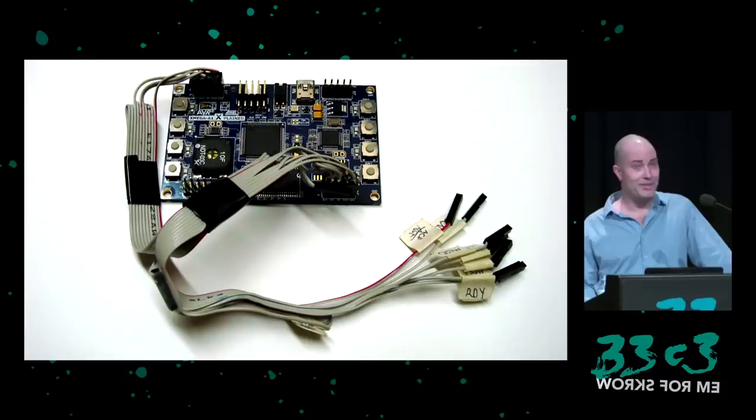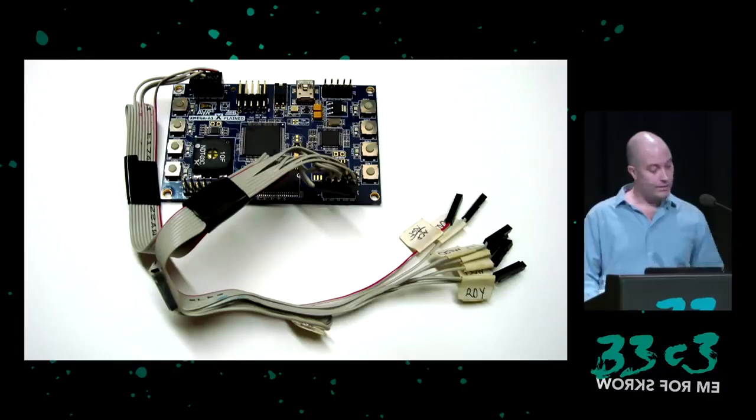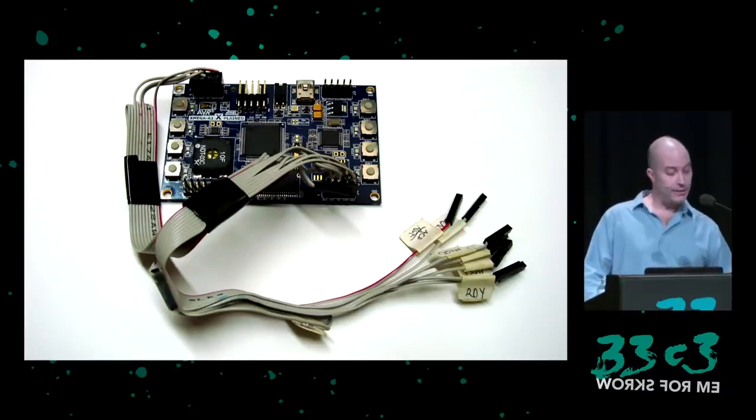It had some limitations, like only accepting 64 kilobytes of data for replay and logging, which was just barely good enough for my studies. What the transport stream logging in-circuit did show me was that the transport stream passes through the ACP with selected PIDs being decrypted, and then the output is the full transport stream, but a selected program has been decrypted. The AVR32 logging interface had rather limited use for me.